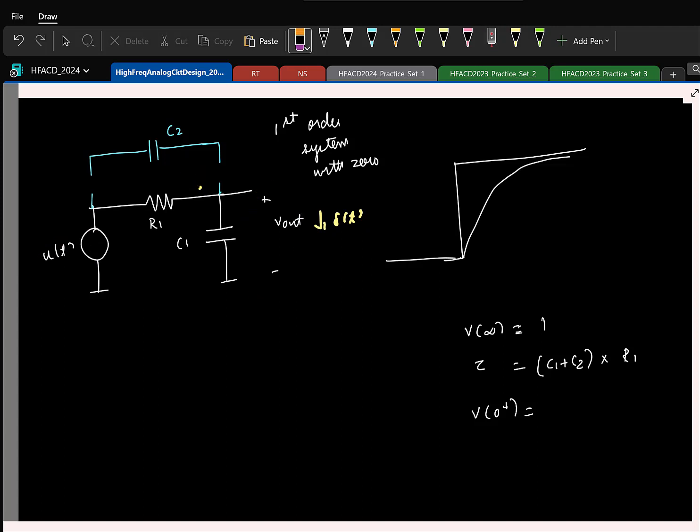That's not possible. But the moment I put this capacitor, if we want this impulsive current to flow through this capacitor, it cannot flow through the resistor. But is there some other path it can flow to? Now if impulsive current flows through both capacitors, both voltages change as a step. Everywhere you have step voltages, everyone is happy, right?